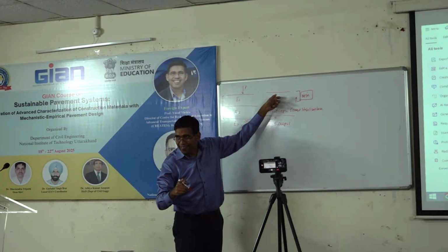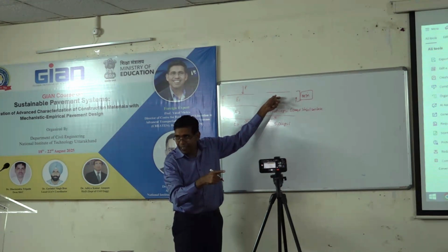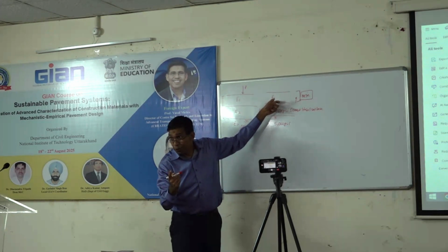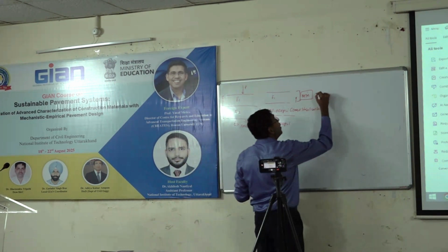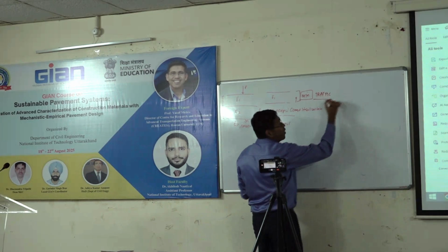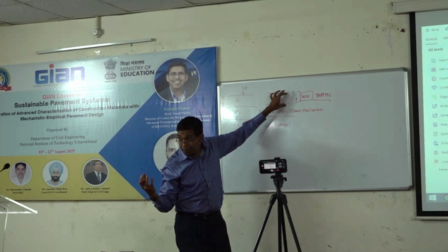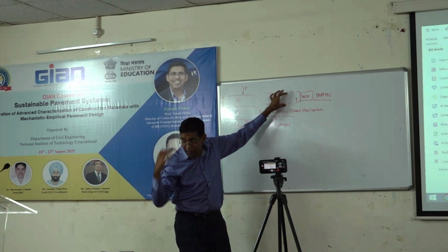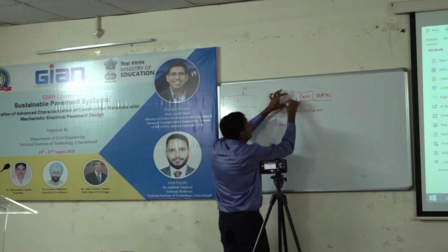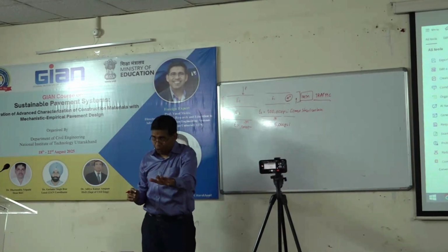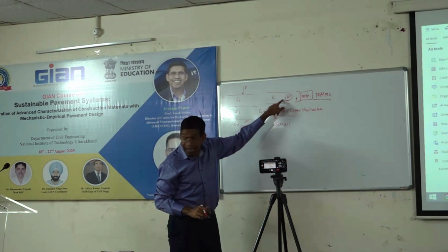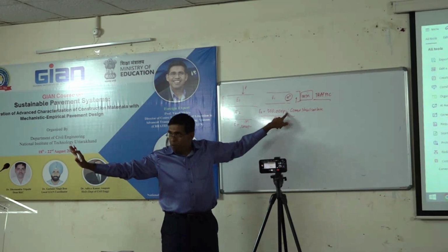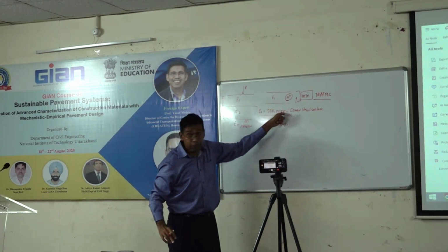What will dictate? I showed you the table there in the textbook. The traffic level. Remember I showed you the traffic level? 6 million, 7 million, 8 million. That traffic level will dictate. So remember I showed you 7 million. This was minimum 4 inches. Correct? You saw that AASHTO table, right? I remember that number. So that is exactly what AASHTO is doing: if 7 million, I told you minimum 4 inches. This is very strong. Ignore your math. You will have to provide minimum 4 inches, even though this is very strong.